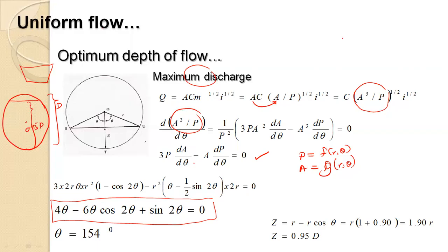So we are still at uniform flow, and we were looking at the optimum sections considering a circular section and a trapezoidal section. Of course, if this is the circular section, don't think that we are going to have very large sections. These are relevant to very small sections, particularly like Hume pipes, which can be brought from a precast yard and then installed, assembled on the site.